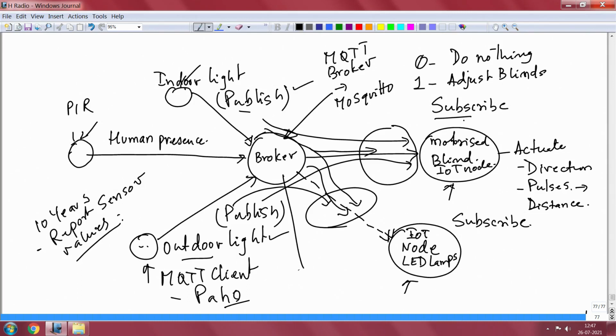Take a Raspberry Pi, and on this you can run Linux or Raspbian, any one of them, and then install Mosquitto. And these are indoor and outdoor nodes, and you essentially run on all the simple controllers that we spoke of, nRF52840 and 52832 and so on, install the MQTT client on those systems, and just keep publishing. This system is over.